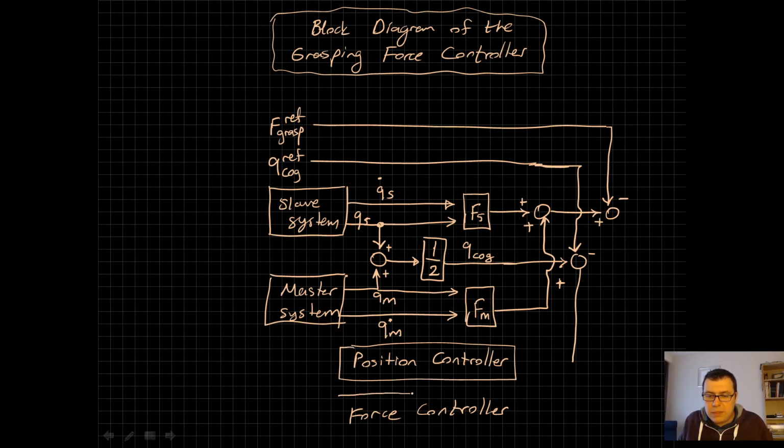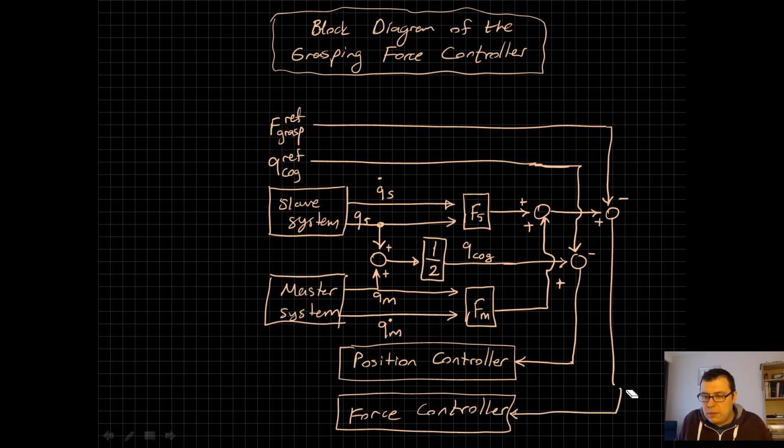These are nothing but our feedback with the derived gains. So your error signal goes to your position control. Your error signal here, this side, will go to force control. And here you have 1 over 2 dE that comes from the determinant of our matrix omega.